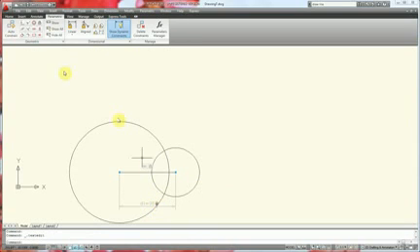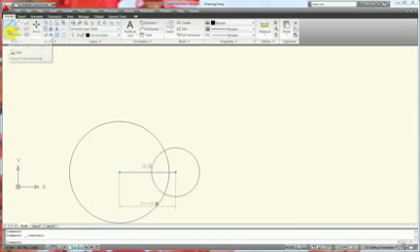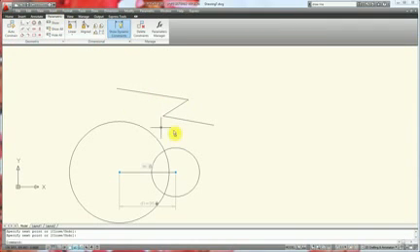Once we've done that, we're going to go back to the Home Ribbon Tool panel and click on Line. And we're going to make a line that looks like a shape of something like this. Right click and choose Enter. And I go back to the Parametric panel, and we're going to try and make this line parallel with this line. So we're going to pick the parallel constraint, choose this line, choose the line we'll make it parallel from. But now notice, however, it moved this line from here. We don't want to do that. We want to bring everything with it. So we're going to undo that.